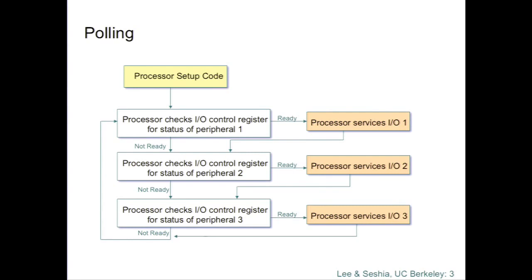And one of the things I mentioned was that there's a family of domain-specific networks that are used in industrial automation, in automotive applications, in avionics applications, and so on. And these are different in character from the networks that we use to carry TCP/IP traffic and internet traffic. And one of the key differences is that these networks are time slotted. So they're reservation based with periodic schedules, and devices have exclusive access to the network for some amount of time at a periodic rate. And this is a way that you can get deterministic behavior out of networks. And that's one of the things that is really the driving factor for the existence of these domain-specific networks, in order to be able to get this deterministic behavior.